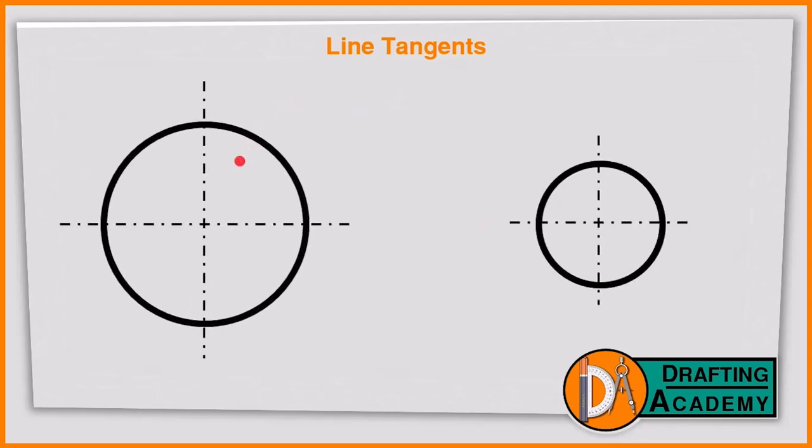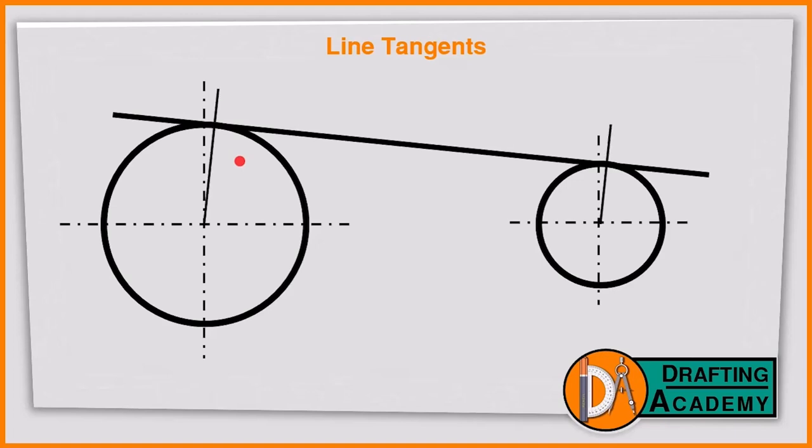Next, you might be introduced to something a bit more interesting, where we have two circles. One might be smaller than the other, or both of them might be the same size, and then we'll have a tangent that will touch both circles like that, and always there will be some normals. The rule of thumb for tangents is that you don't draw a tangent before you have drawn the normal. The normal is what tells you at which point the tangent is going to touch your circle.